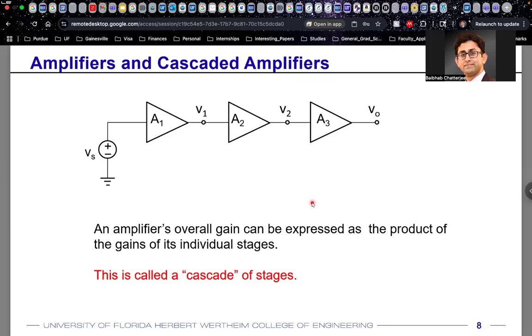However, there are possibilities, and you know that circuits are all about non-linearities and non-idealities. You will see that in certain conditions, your gain will not be a linear gain and your output may not be gain times input. And in that case, what it might look like is something like this. And this is very real in all amplifiers. Every amplifier that you encounter in life may look something like this. There would be a linear range, and then there would be a range where your output saturates. As you keep on increasing your input, your output will not increase anymore. Your output will saturate, and that region will be called the region of nonlinearity.